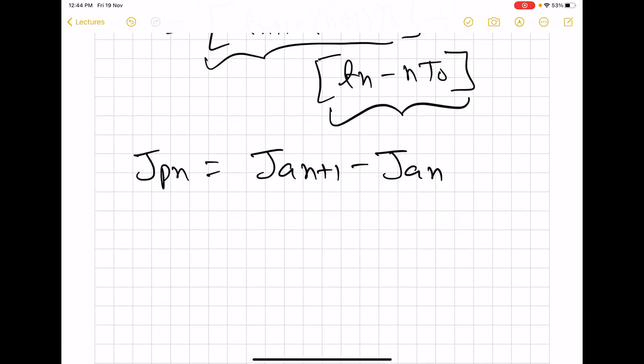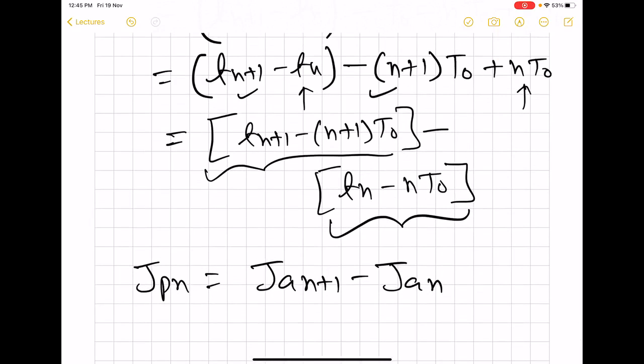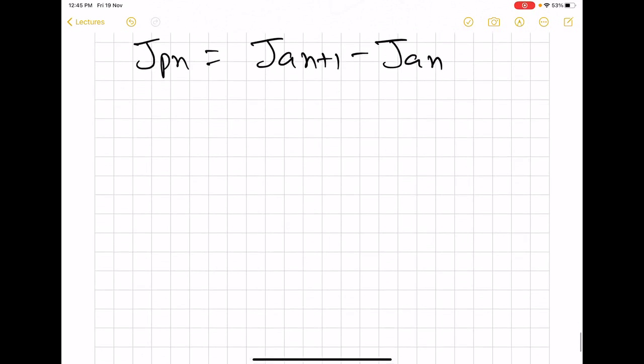So here what we have done is find out the difference between the time period of one cycle with respect to the ideal clock. But sometimes, for example in the case of a divider or counter, we are interested in knowing the deviation of the final clock edge with respect to the ideal divider. In those cases, we do not try to find out the difference between one period of the non-ideal with respect to the ideal.